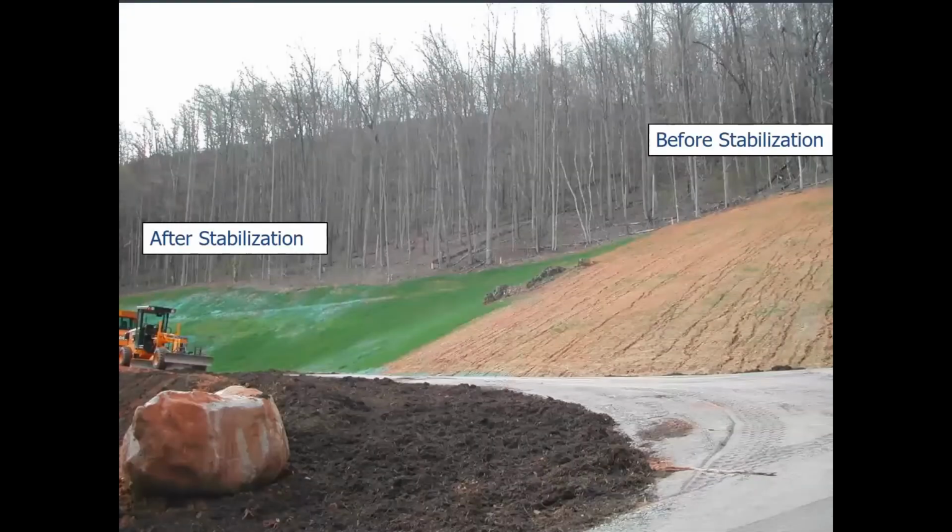I call this my Friday afternoon slide. So you can see they've stabilized the slope at the far end with grass, and in this case they used hydromulch. We'll talk about different kinds of mulches later. And then on the right, they didn't get around to it, and so they had a rainstorm and look at all the rills. So they're going to have to come back and work that again, reseed it. So this is a good example of once you get to final grade, once you get the slope the way you want it, it's good to get it covered up immediately, because you never know when a big storm is going to come along.